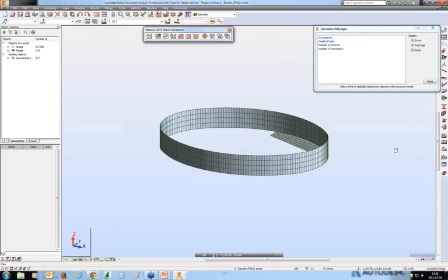And after that, we switch on this reduction option, and I think that's the answer for your question. You may also try to create rigid links from the common nodes or bar elements of the pile, that's my assumption of how you model it, and the panel, and simply create a sort of rigid surface to reduce the peaks directly over the supports.